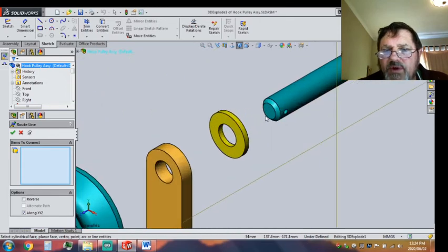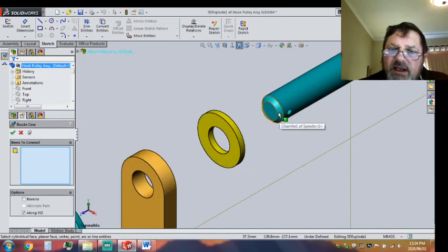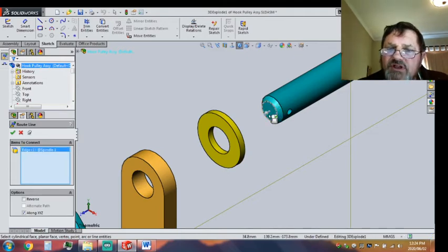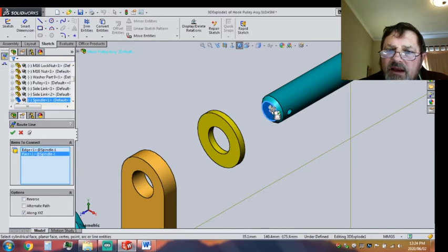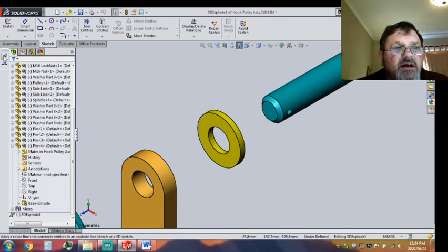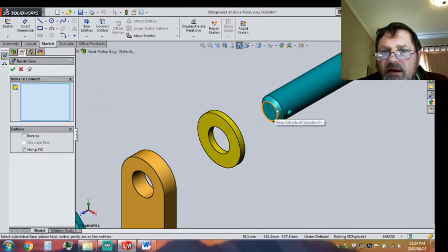So now here, and with the mating, we did all the surfaces with root lines. We're going to select edges. Now you'll notice the arrows coming that direction, which is correct. If it's not the right direction, you just click the arrow, it changes direction. Click there, wrong way, click there, oops, wrong way, click there, oops, I think I'm making trouble, so I can go out there, click that one again, click there, I've got it in the right direction.